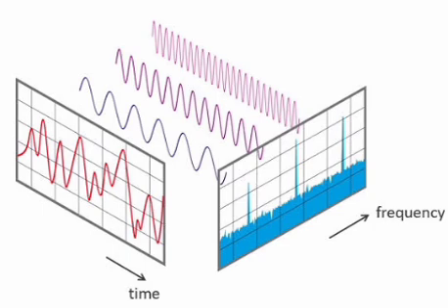Causal IIR systems are characterized by the constant coefficient difference equation or equivalently by the rational transfer function. From these equations, it can be seen that the realization of infinite duration impulse response systems involves a recursive computational algorithm. In this section, the most important filter structures, namely direct forms 1 and 2, cascade and parallel realizations for IIR systems, are discussed. H of z equal to y of z by x of z equal to sigma k equal 0 to m, bk z power minus k, by sigma k equal to 1 to n, ak z power minus k.